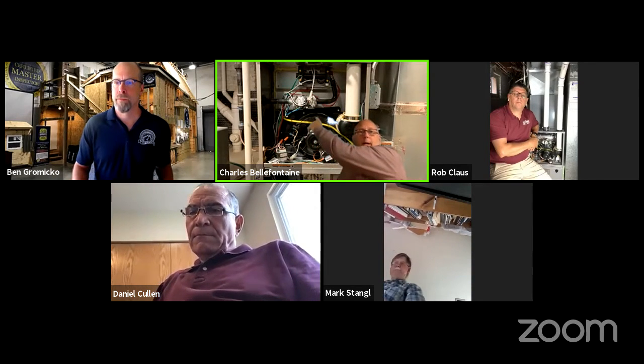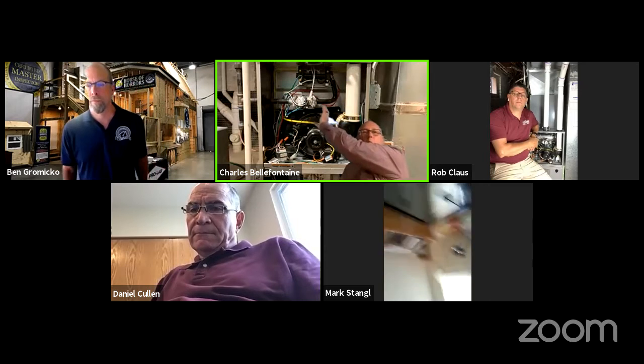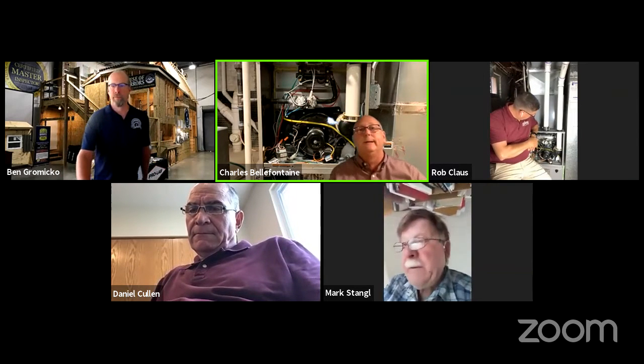If they don't, well, then there's a possibility that our blower fan's on the wrong speed, or maybe our air conditioning coil is clogged. That could just end up being a lot of other problems. Other sensors: way in the back, you'll see a couple lines going in there, and there's going to be a square little thermostat or sensor in there.